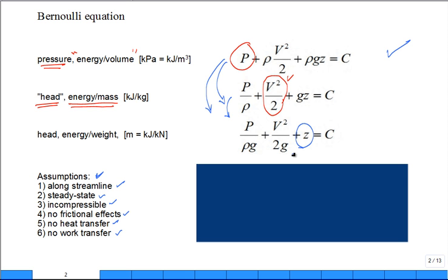All right? So z, just meters. And you think meters, that everything in this whole equation has units of meter, meter, meter, but how can you interpret that as energy? That's challenging, probably more challenging than pressure is energy, but it's energy per unit weight. Weight of what? Weight of the fluid packet that's flowing through the system. This one is head. This is commonly called head.